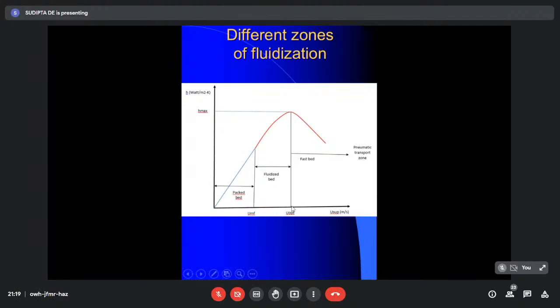So you have to decide what should be the optimum superficial velocity for getting the maximum heat transfer coefficient. Deciding this point corresponding to the maximum heat transfer coefficient is the essence of deciding the operating point of a fluidized bed heat transfer. Anyway, do you have any queries, or can I just give the text dictation? Just write down,